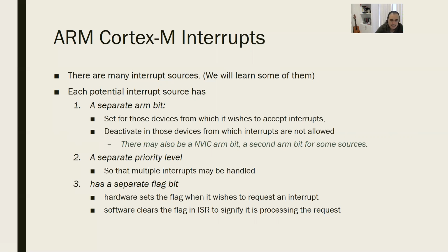Guys, interrupt can happen because of many things. Maybe an input came to one of the pins or multiple pins. We have 8 pins in a single port. We have 6 ports. We have 48 pins in total. All of them can create interrupts and separate interrupts.